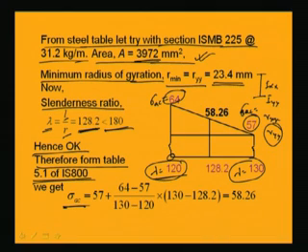Now, we have to find sigma AC for lambda equal to 128.2. In this case we will make a linear interpolation between the 2 points.